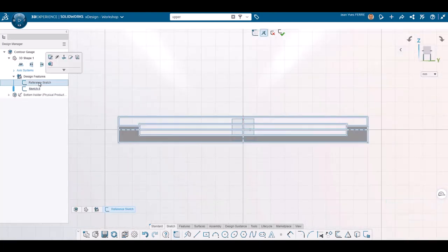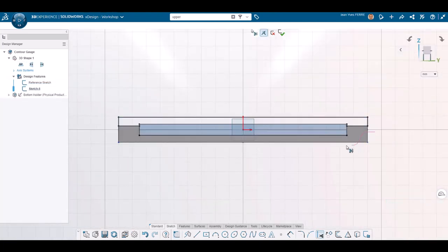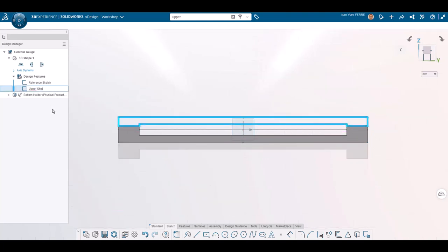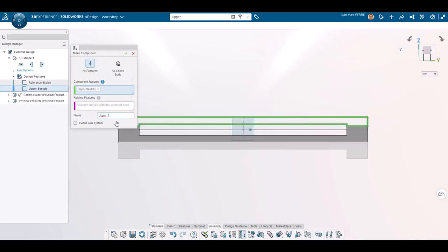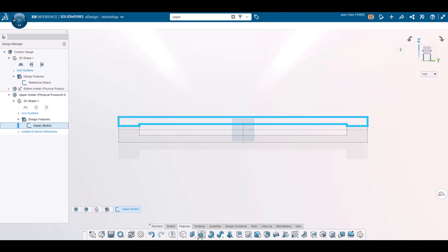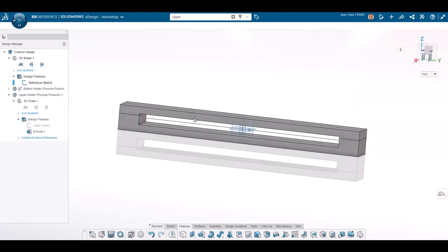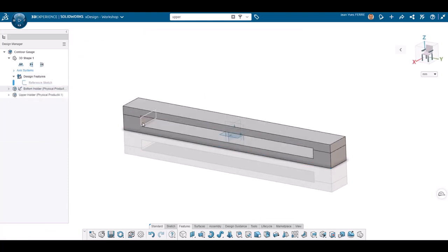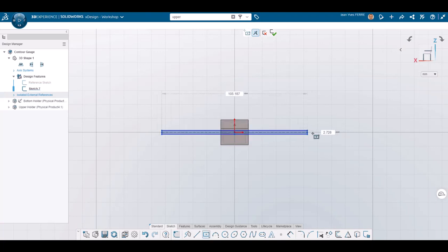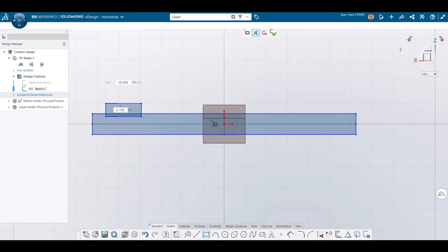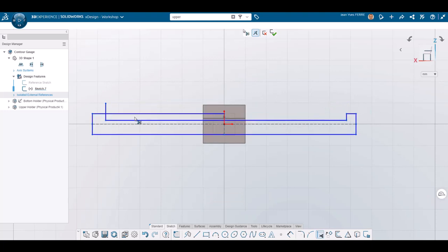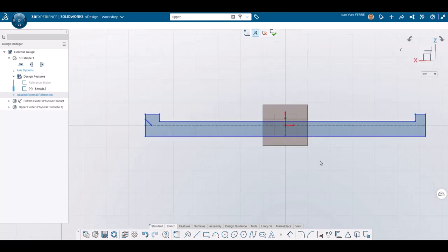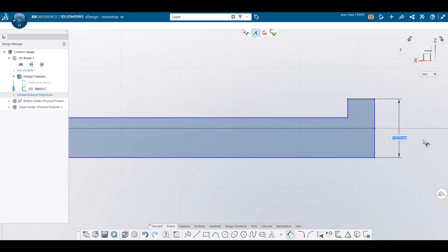For the second part, I will do it slightly differently. I create a part from the sketch. Then I activate the part I created so the next extrusion is added to the component and not in the assembly. In the other direction, I create the profile for the white blades that will slide to capture the contour. Please note I only make one half and create dimensions across the axis to transform them into symmetrical dimensions. This is one of the many nice features making life easier in xDesign.